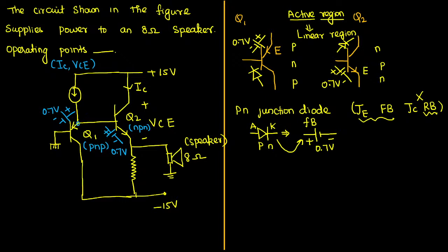Now, can you please let me know what can be the expected voltage here? I'm just highlighting this point to focus on it. I just wanted to know the voltage at this point. I'm calling it Vx. I just wanted to know the value of Vx. How can we identify it? If you keep attention on the base terminal, what is the value of base voltage VBB here? VBB is 0 or not? The value of VBB is 0 volt. Why, sir? Because it is connected to the ground. If it is connected to the ground, then its corresponding voltage will be 0.